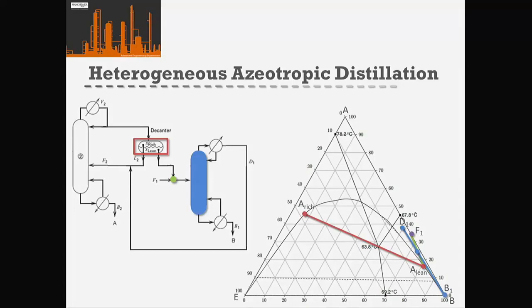The reason that I've not drawn residue curves on this diagram is that there'd be so many lines on the diagram that you wouldn't actually be able to track redrawing the distillation sequence on. Okay? So we've now specified the liquid-liquid step and our first distillation column. Okay? So we only have our second distillation column to go.